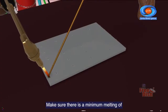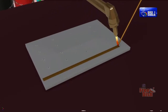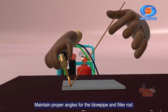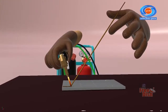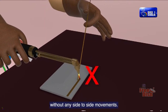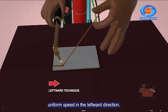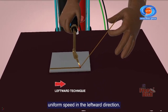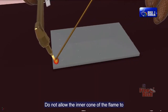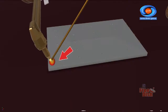Make sure there is a minimum melting of the base metal and filler rod as possible. Maintain proper angles for the blowpipe and filler rod. Move the blowpipe and filler rod without any side-to-side movements. Move along the marked line at a uniform speed in the leftward direction. Do not allow the inner cone of the flame to come in contact with the molten metal to avoid backfire.